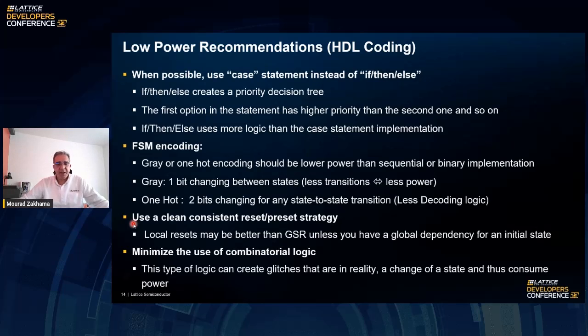It's a big topic, but resets are usually high fan-out signals, and having multiple of these globally distributed to the whole design can create a lot of routing congestion and a lot of power consumption. So having a clean, consistent reset strategy is another thing you could do.